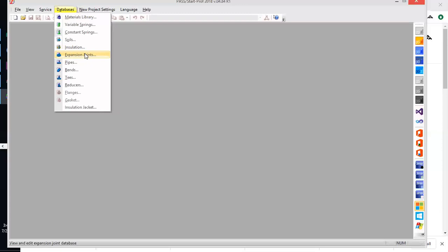Okay. So when we talk about expansion joints, metals generally don't keep a state. Once there is high temperature, they expand. Once there is cold temperature, they contract. So the function of the expansion joint is to keep your pipeline within the design limits during the work time.